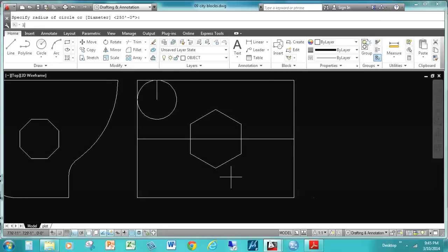Then let's draw another line from midpoint, snap to the midpoint, and go up. We have to make sure it's really 200 feet. So for this reason, we shouldn't assume that here's midpoint, although it shows the midpoint. So line, enter, click here, go 200 feet, enter, and go up 75 feet, enter. So usually it's correct when it shows midpoint, but in this case I might have multiple parts of line.